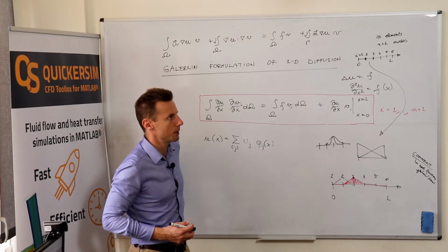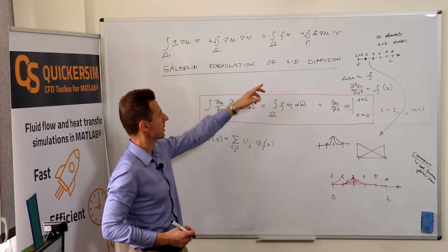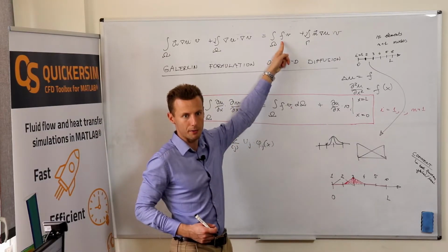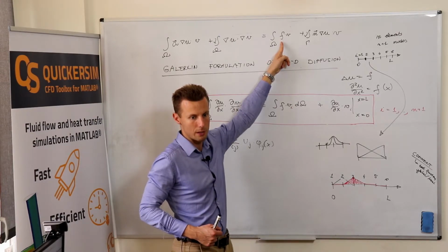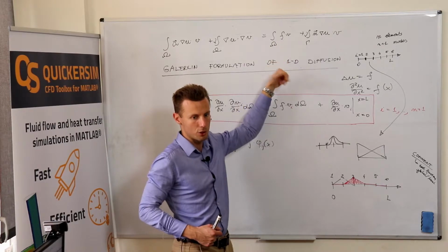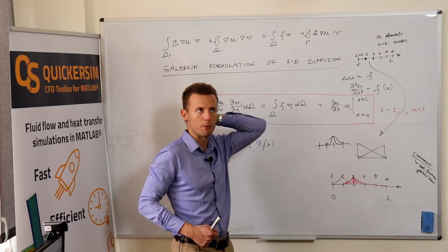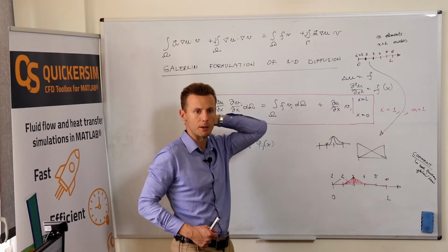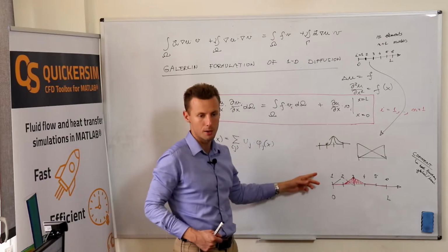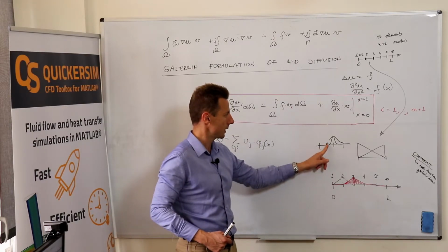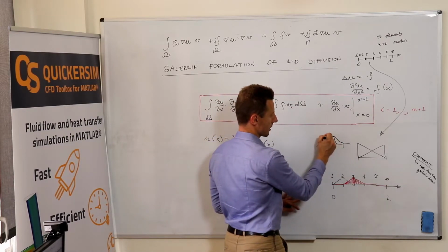And I think it's not difficult to show. Mainly because if you want to discretize something like a source term, which is everywhere 1, and your shape functions do not fulfill that, you would end up with wrong results. I think it's pretty easy to show that you must fulfill this requirement of partition of unity. And if you take something like that, you might end up with a field which is like that.